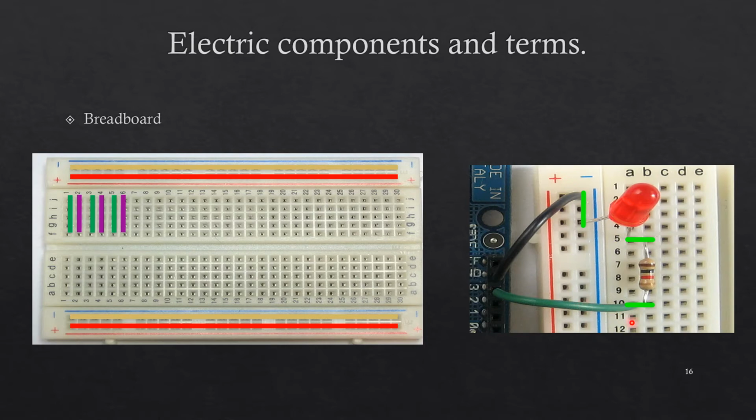And also you can connect your resistors and your LED using those vertical lines. You should not connect the same component along the vertical row. You should be connecting the component horizontally across the vertical rows, because otherwise you would be connecting the 2 pins of that component to each other, and then you can't use it.